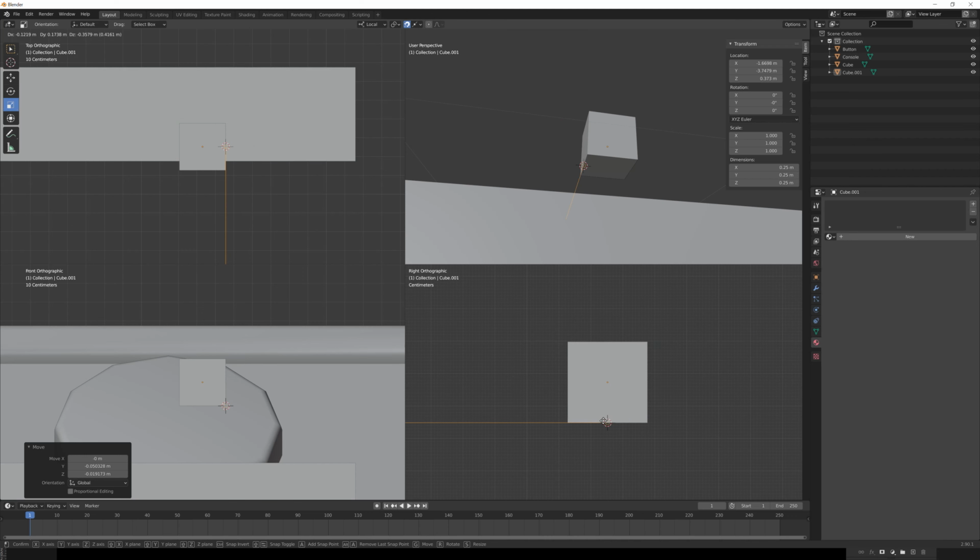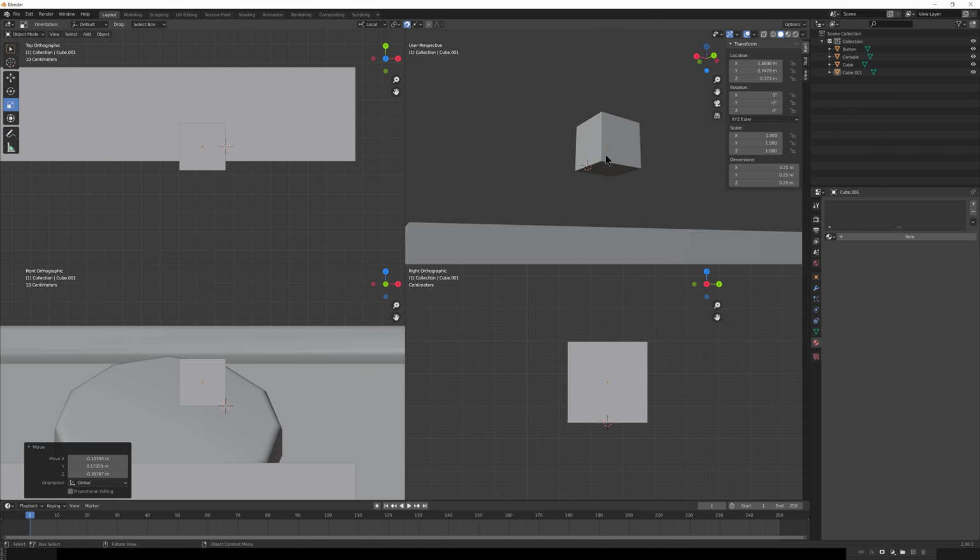So in this case, we're going to say snap it to this bottom side over here. Now as we can see, it's snapped to the center point. Why? Because in my snap settings, I have edge center selected. All right, so that's going to snap to the center of that edge. However, I actually want this to be dead center in the box along the bottom face.